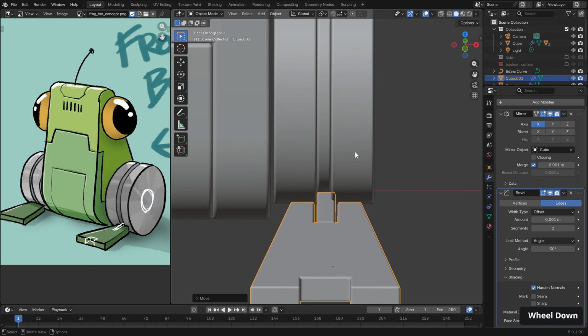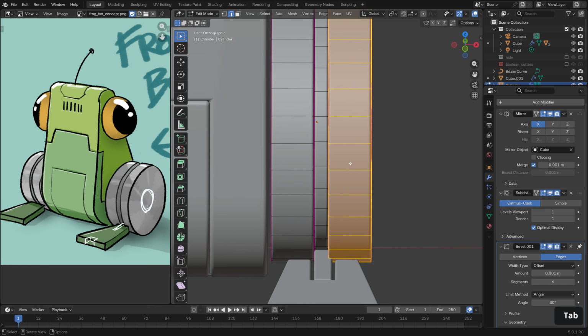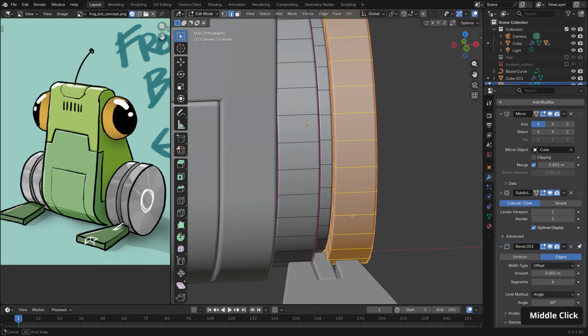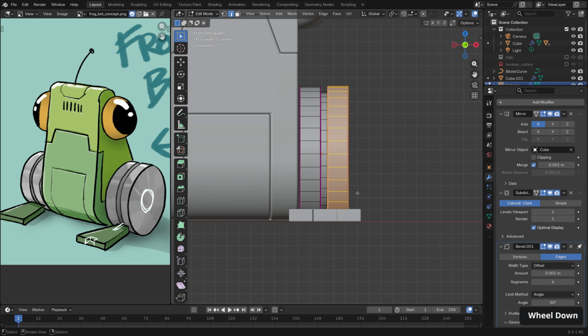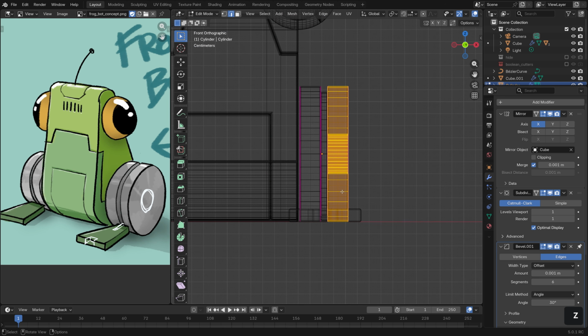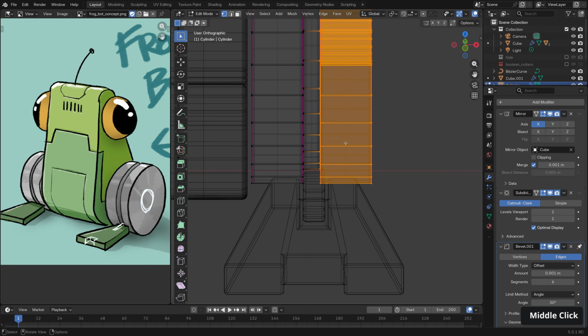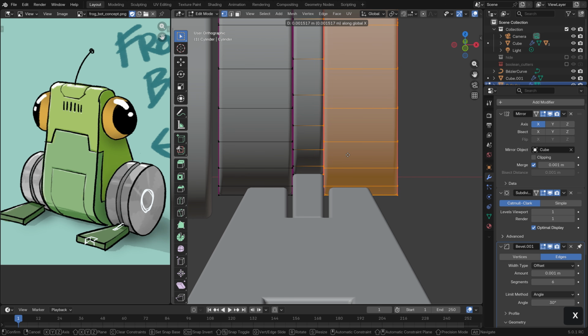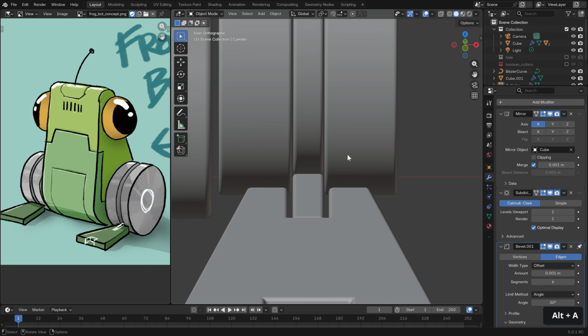one side. Then select our wheel here, going into edit mode, snapping to the front with Alt, going into wireframe with Z and wireframe, and I'm going to switch to vertices here and just select everything one side, move in for a closer look, maybe switch back to solid for this, G and X, and move it out until it is flush like so.